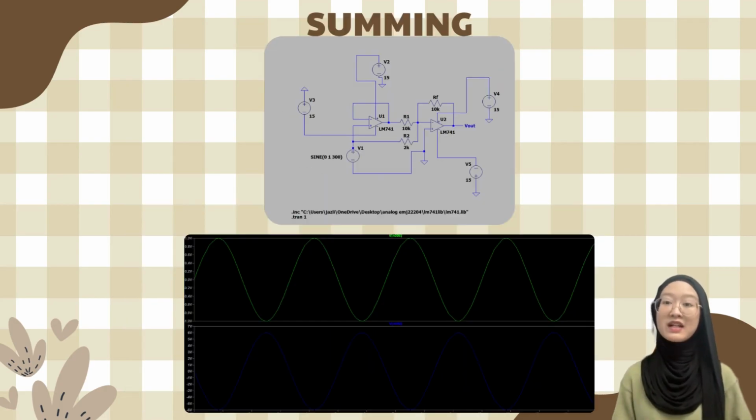The integrator uses a capacitor in the feedback path instead of a resistor at the input. The output is proportional to the time integral of the input voltage. When a square wave input is applied, the output is a perfectly shaped triangular wave. This is because the integral of a constant is a ramp. The op-amp is constantly charging or discharging the capacitor, resulting in a linear output.